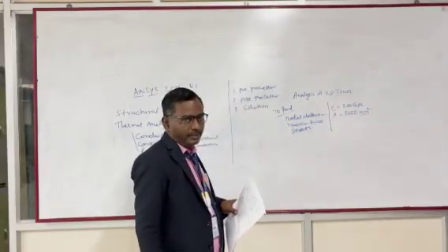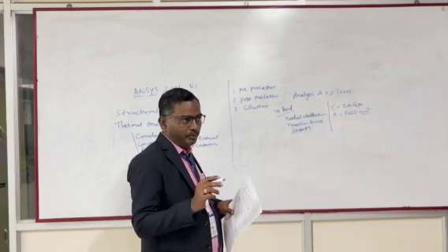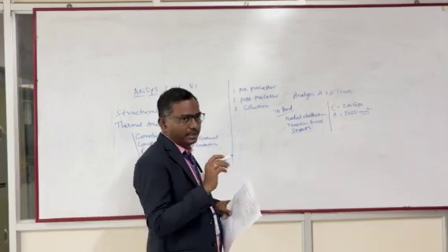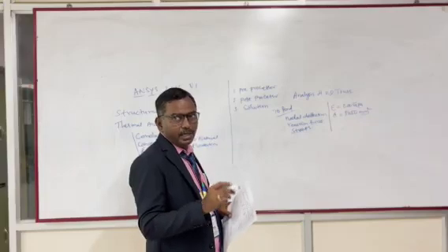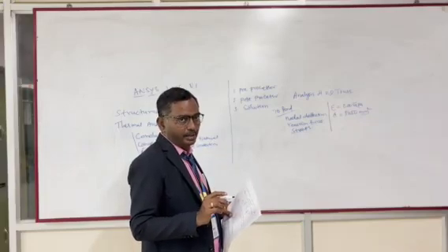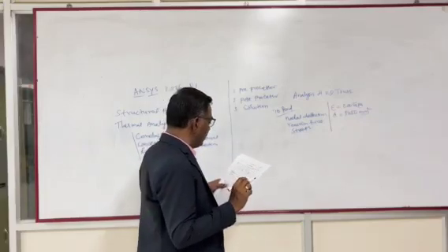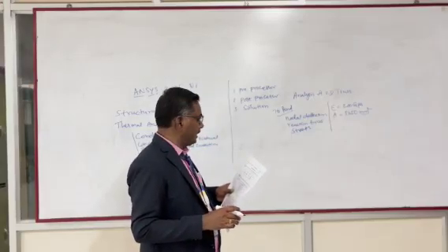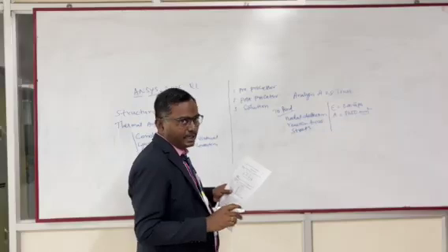If it is given in mm square, you can use all values in mm throughout the problem. Otherwise, if you are using meter squared or meter, then throughout the problem we have to use meter. That is the main thing. Otherwise, the result will be different and an error will occur in the final result.